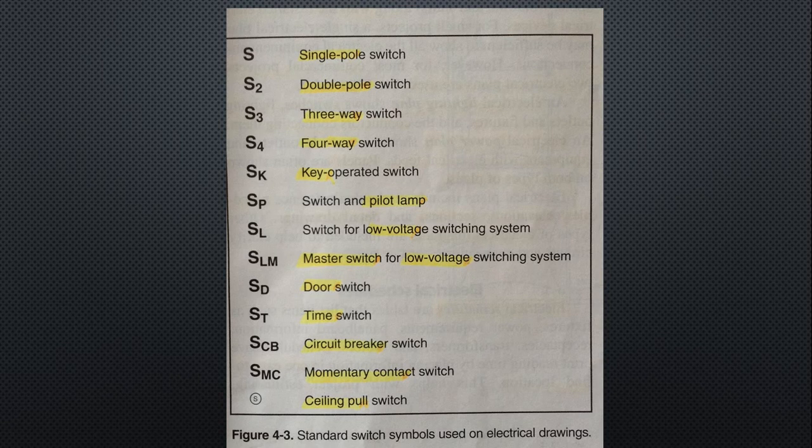Circuits without conductor marks are assumed to have two hot conductors. If all the circuit lines are drawn back to the panel, the drawing would be very crowded. Therefore, an arrow at the end of the conduit line signifies a conduit run back to the panel. Normally, the panel and circuit is identified next to the arrow. The number of arrows at the end of a conduit line indicates the number of circuits whose conductors are contained in the conduit. For this, see figure 4-2 in the text.